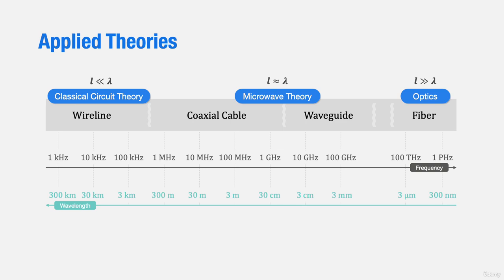You might find it strange that we use microwave theory to deal with signals at lower frequencies, such as 1 MHz or 2 MHz, which frequency seems not so high. However, the answer is that it depends. As we mentioned earlier, when the signal frequency is higher or the wavelength is shorter relative to the line, the transmission line effect will be relatively apparent.